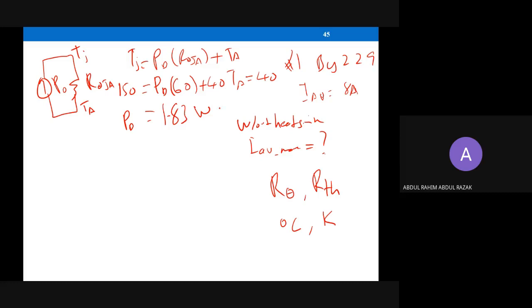So how many ampere? For a semi-controlled or fully controlled device, you will have a direct plotting graph of PD versus I. If you open your datasheet number 1, page 3, we have figure 2 and figure 3. You can see there P forward versus I forward average.